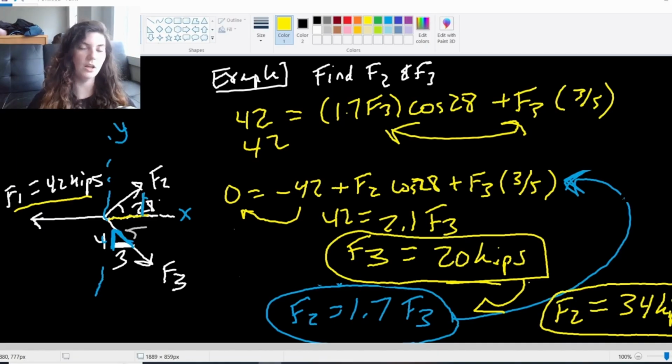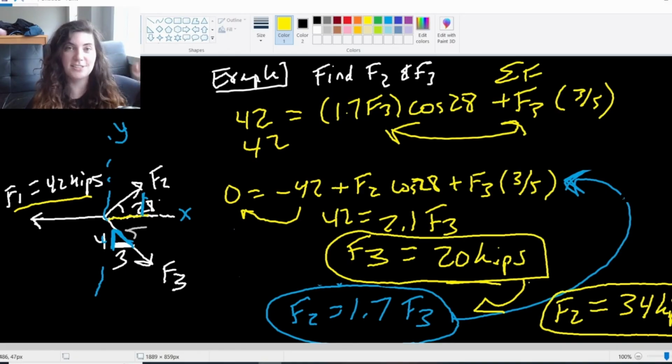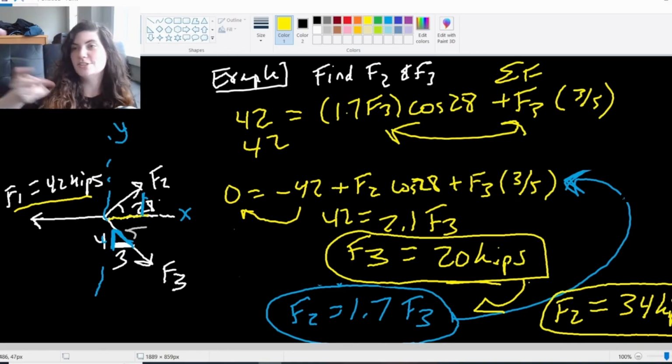It's just going to be a lot of setting up and solving these systems of equations. So that's why it's so important to have these free body diagrams correct, so that you can see exactly what goes into these summation equations. It's really important because it's so easy to make a sign error or an angle error, a sine and cosine, not just a sign error in both senses, a negative sign versus positive sign, a sine versus cosine.